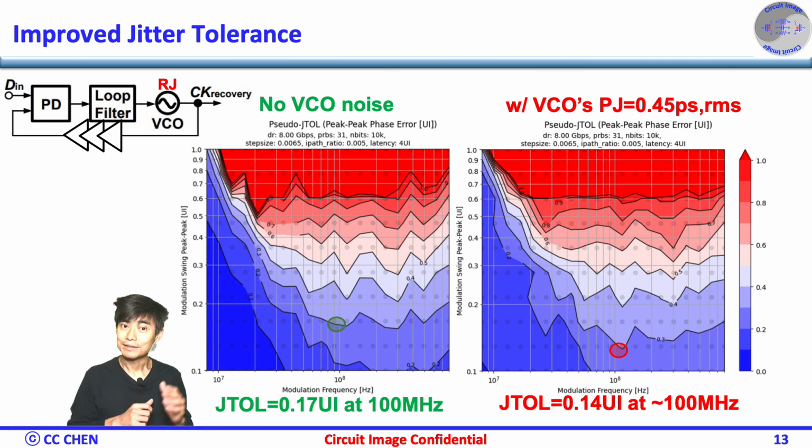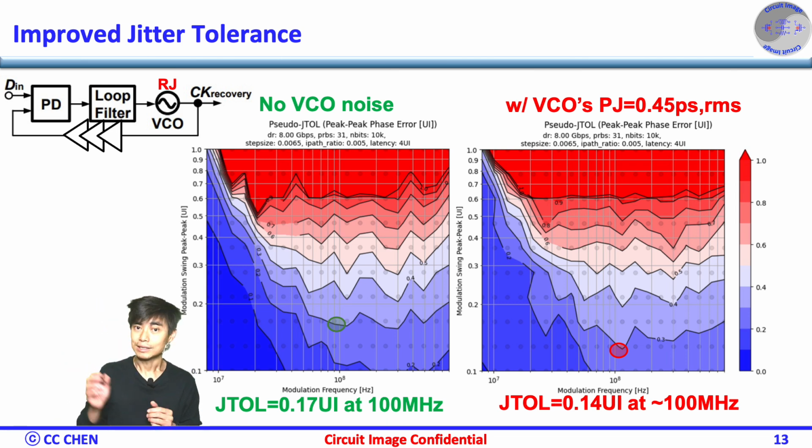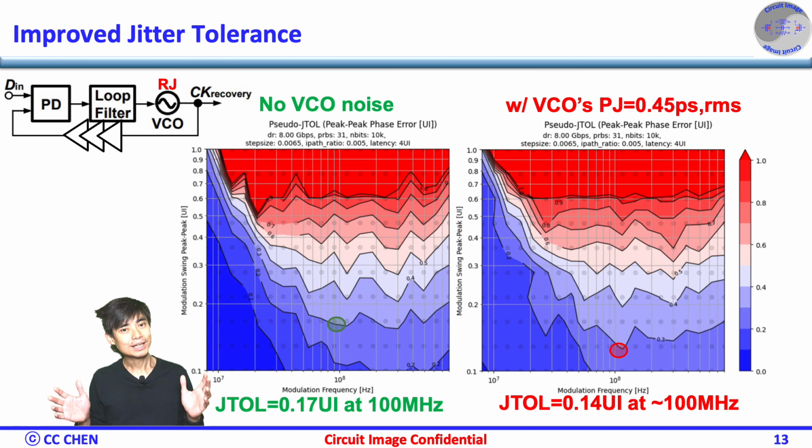Since the receiver's clock is running at half the data rate, it inherently has more tolerance to timing jitter and phase variation in the incoming signal, owing to less intrinsic RJ and less jitter generation from the DDJ. Even though the half-rate CDR has more latency than the full-rate, there are other, smaller jitter sources in half-rate that can still make it have a better jitter tolerance than the full-rate one.